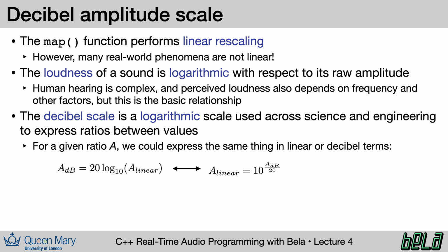Notice that here we have 20 times the log base 10 of the linear value. The reason for this is a bit more complex, and it has to do with measuring power versus measuring signal amplitude. We're not going to go into it here, but just perhaps take it as a given that we can use these formulas to convert back and forth between signal amplitude in decibels and signal amplitude in linear terms.